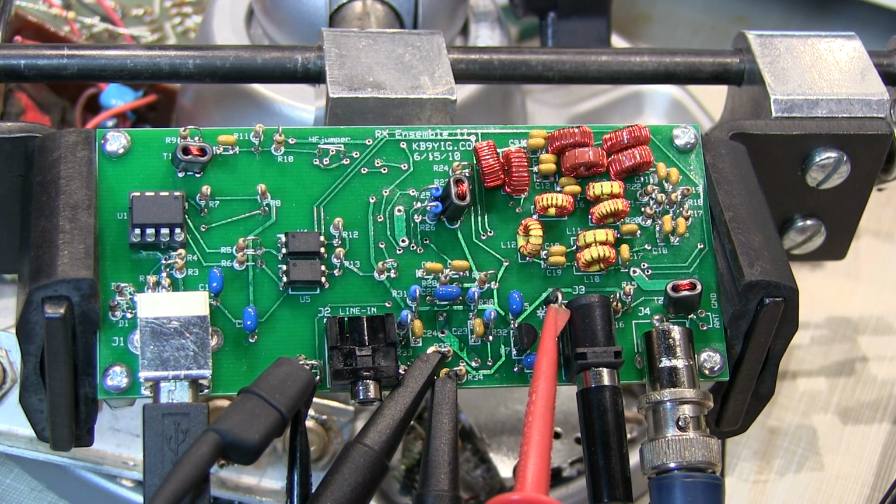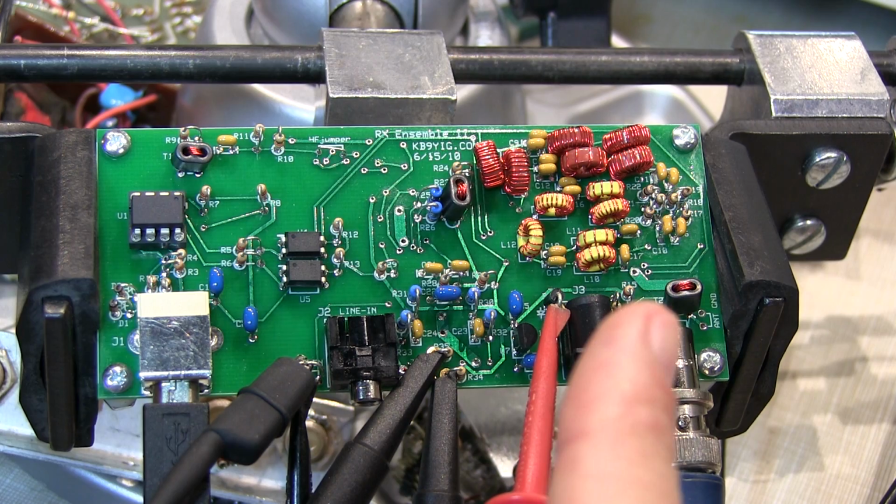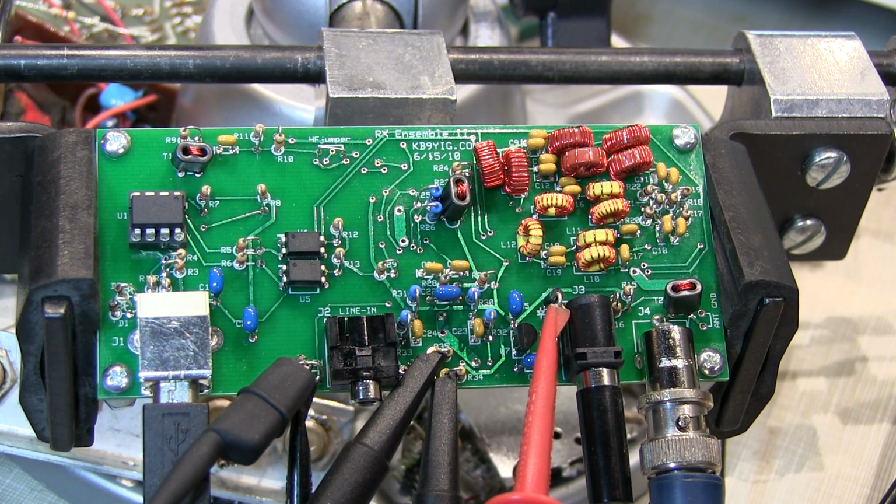The sample rate of the sound card that's used determines essentially how much bandwidth you can see, listen to, and tune across in the receiver. A higher performance sound card with a higher sample rate will allow you to look at a larger spectrum. But it really is a neat little process and an amazingly small amount of circuitry to form a really nice, well-performing receiver.